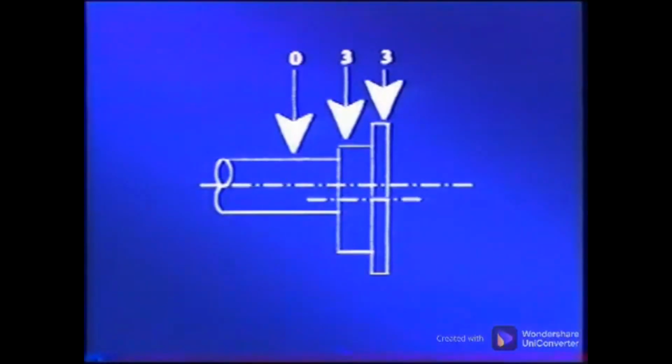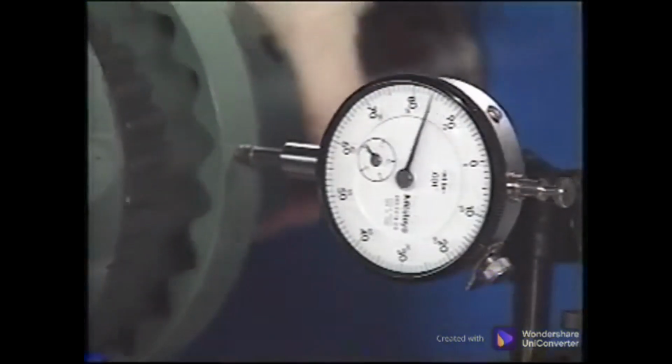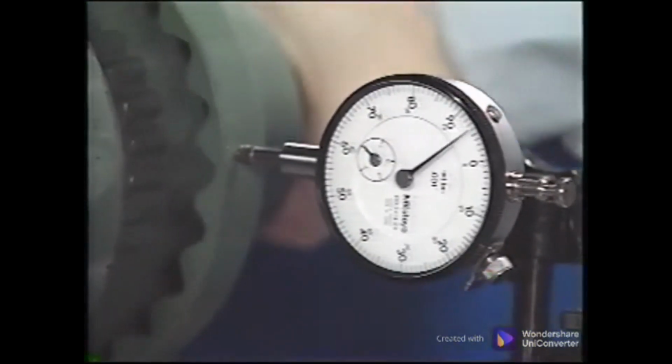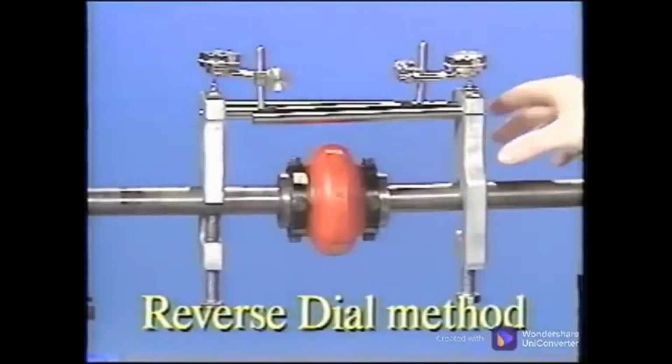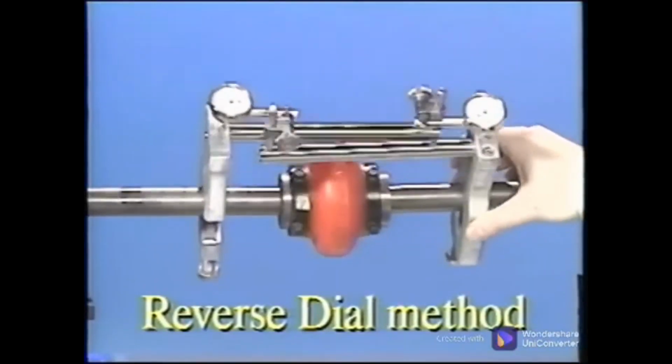When using the face rim method, it is critical that the coupling is true. Often couplings may be bored off-center or at an angle, which then causes the outer rim and face to be eccentric or have runout. Since the corrections for misalignment are based on these surface measurements, only a trued coupling will produce adequate results. The reverse dial indicator method is used when both shafts can be rotated together.